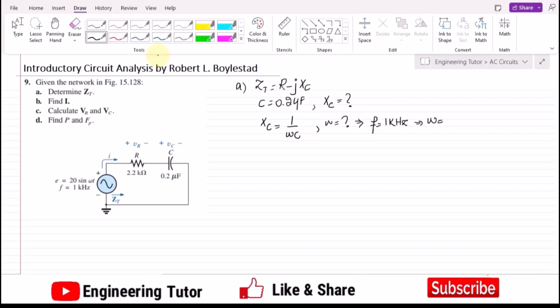Omega is the radian frequency, and that is 2 pi f. Putting in the values, omega is 2 pi into 10 raised to power 3. Now putting it into the formula, X_C is 1 over 2 pi into 10 raised to power 3, multiplied by the capacitance 0.2, and micro is 10 raised to power minus 6.